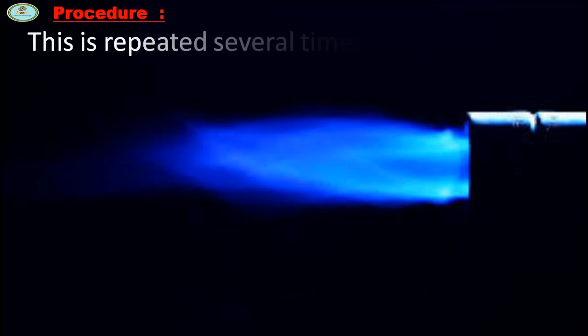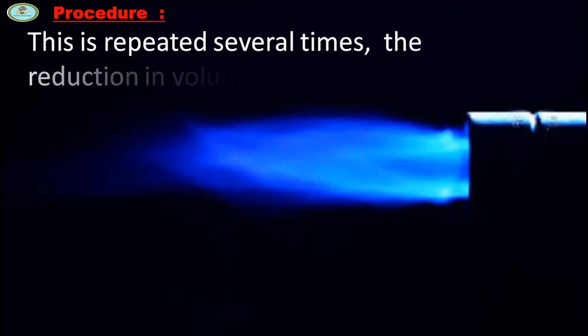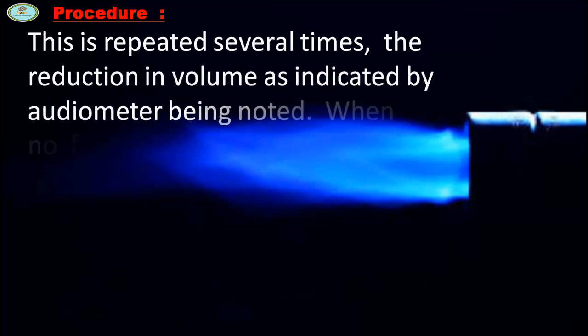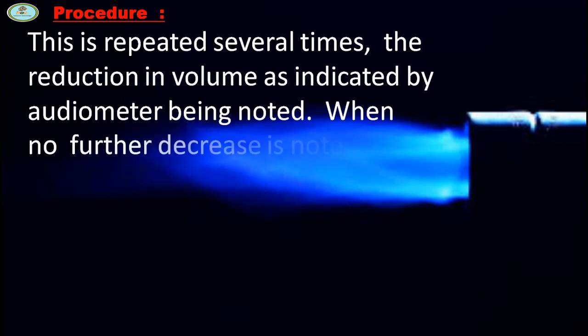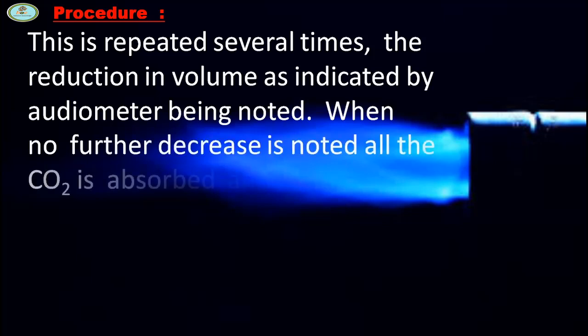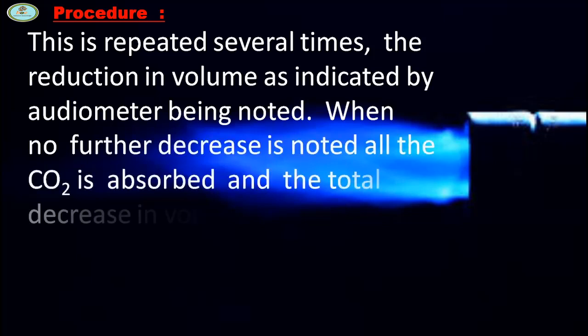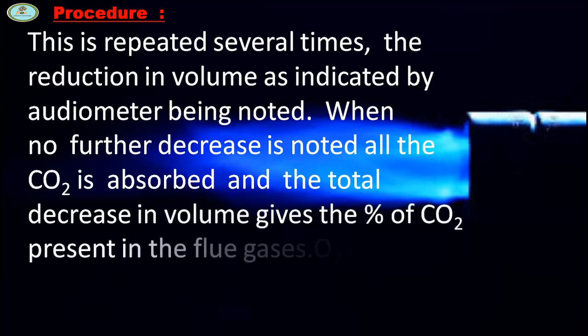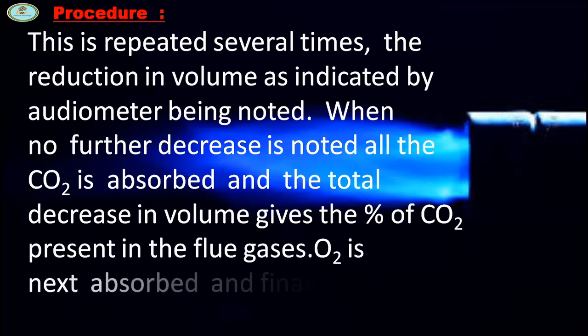This is repeated several times, the reduction in volume as indicated by the eudiometer being noted. When no further decrease is noted, all the CO2 is absorbed and the total decrease in volume gives the percentage of CO2 present in the flue gases.